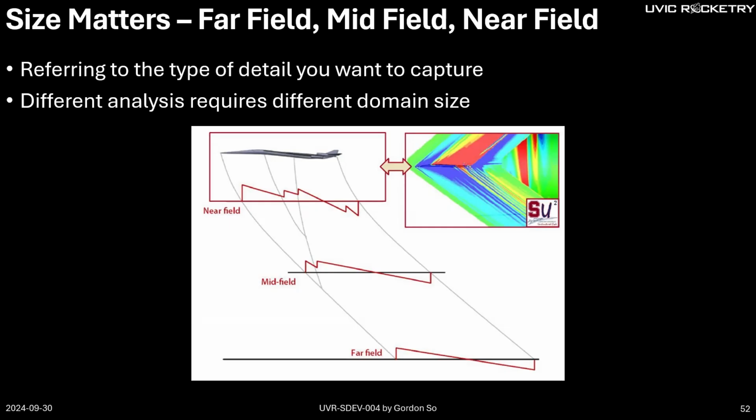So this is a good summary to show you what is different in the far field. But again, this is different. And usually you want to capture as big as possible because your software may interpret certain things wrongly. Because if your far field is put near field, it's no longer a far field. So you're applying a wrong boundary condition. So shape is different and they have their own strength.